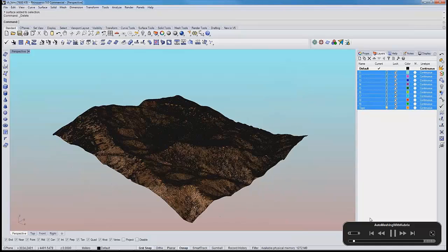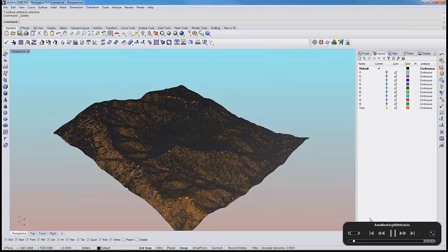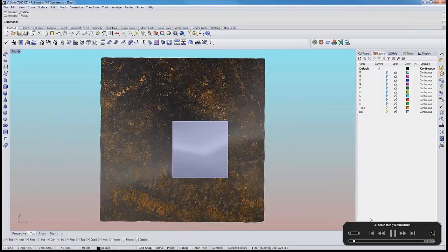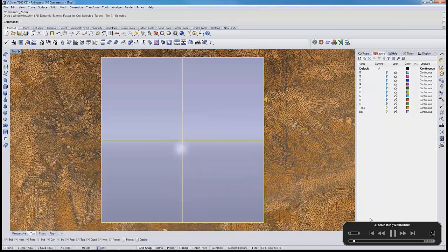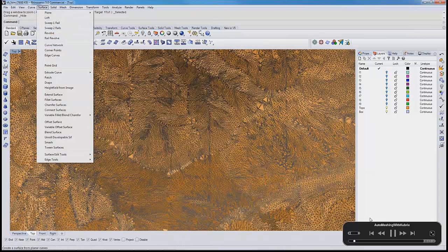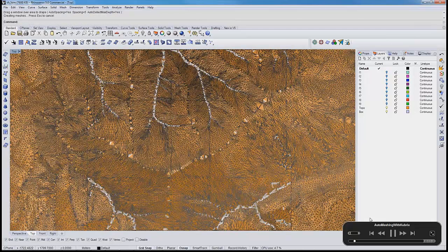Here we're going to get rid of this first surface that we have created through the patch command, and instead revert to the drape command, which is our favorite surfacing tool. And before we drape this surface, we are going to define the computational domain, which is going to be this box here. That's where at the end we would like to create our FLAC3D and 3DEC model. After I defined that box and zoomed in on the neighborhood of that box, I'm going to use the drape command and draw the rectangle that will then represent the draped surface.